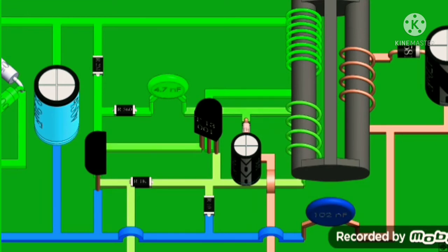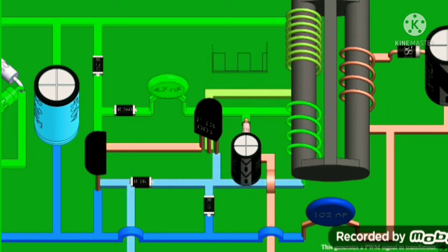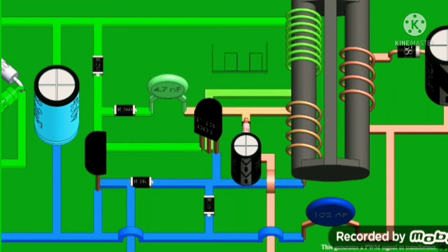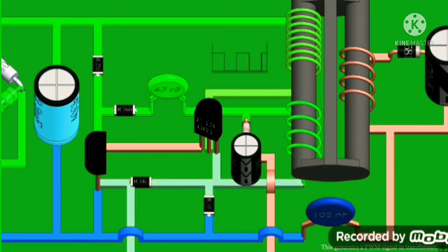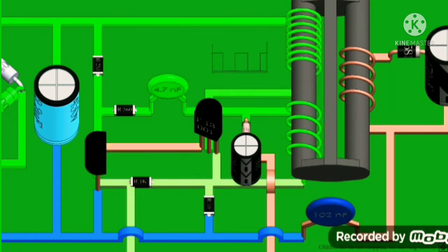Now, this turns on the transistor T2. This shunts the base of T1, turning it off. As T1 turns off, the flow of current to T2 is cut off. Now the current flows to the base of T1 and the cycle repeats. This happens at 15 to 50 kilohertz, which is 1,000 times faster than the rectifier circuit. Hence, you would see that the rectifier circuit is stopped.